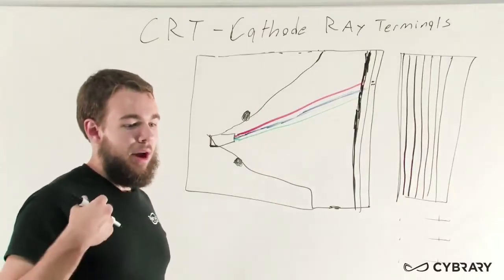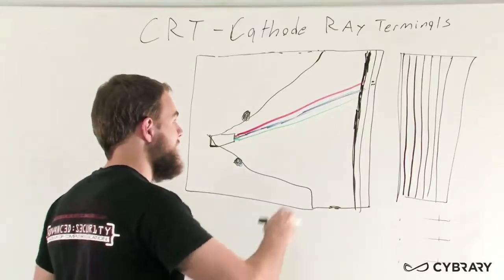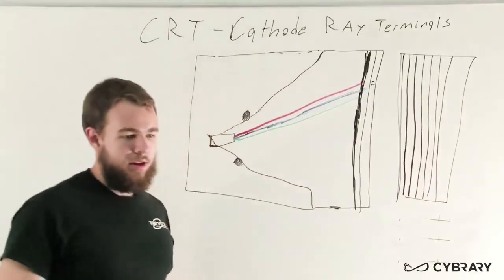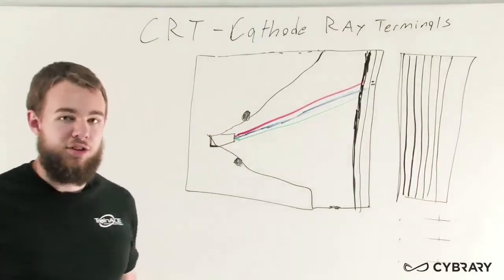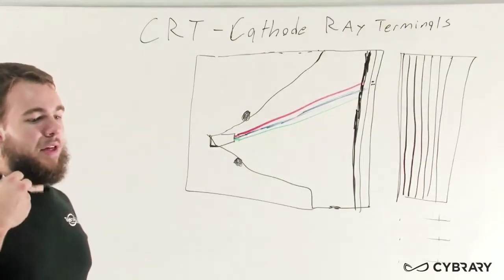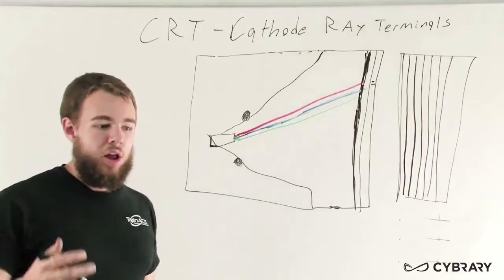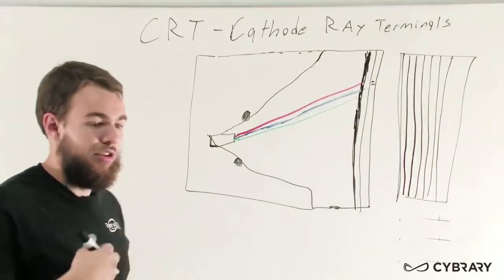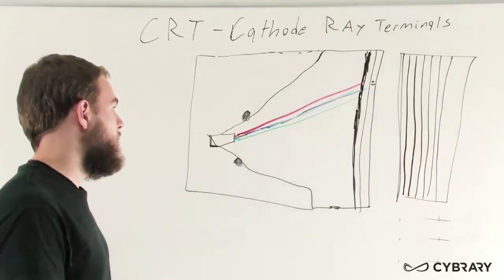which the beams have to pass through, and it deflects some of these off-center beams. You may also hear a slotted mask, and a slotted mask just combines this pixel triad with the aperture grill in order to create a double sense of security in its shadow mask. So again, the shadow mask can have a pixel triad, an aperture grill, and when you hear slotted mask, you're thinking of both of these technologies added together.